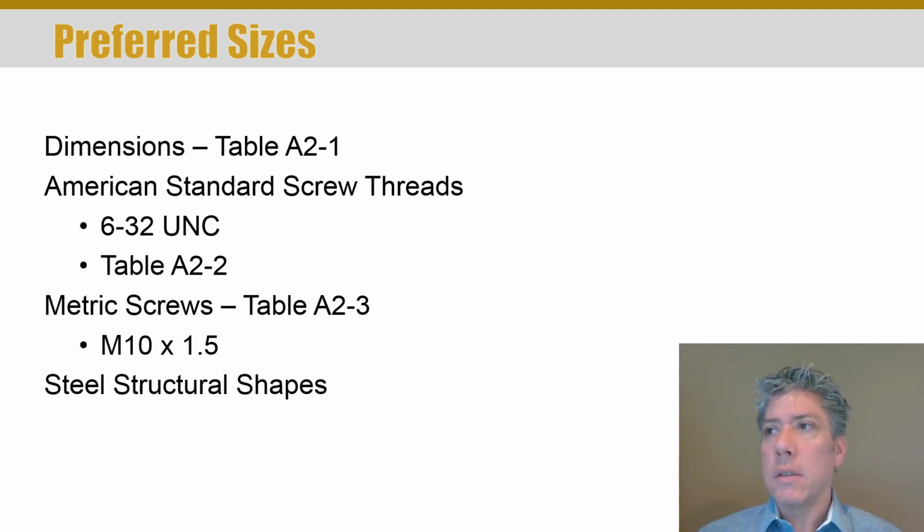Why? Well, imagine trying to ask for a fastener that is 0.2408 or 9 or whatever it was inches in diameter. Well, that's not a standard size, and you're going to pay quite a lot to get a custom fastener like that. Not only that, but when you're designing even a plate or locations of holes in a plate or anything like that, you'd rather use preferred sizes, unless there's a very good reason for not using them.